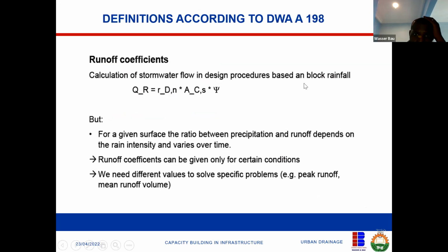So this is just storm. So how do you calculate storm? Our aim in every hydraulic system, like what we're doing today, is for you to get your Q. It is the process of getting the Q that might be cumbersome and involve a lot of what I call hydraulic gymnastics. Okay, you do a lot. Like for instance here, your runoff discharge is the rainfall intensity multiplied by the catchment area multiplied by what we call the runoff coefficient.